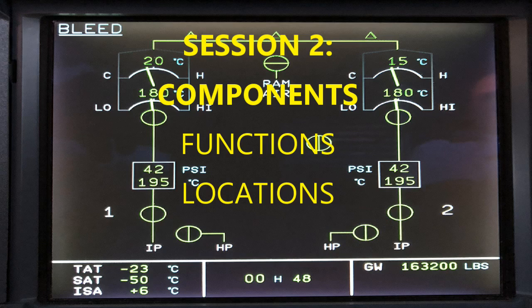Your load valve is going to either allow or not allow the bleed airflow from the APU to the systems. That valve is kind of an off-on situation because it doesn't control how much airflow is going through. It's just either going to stop it or allow it, one of the two. It's just a shut-off valve is all that is. So what happens here?